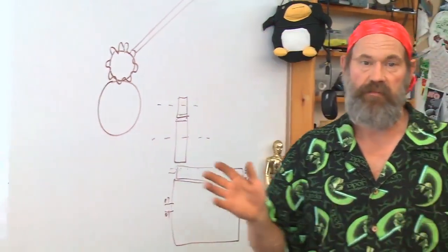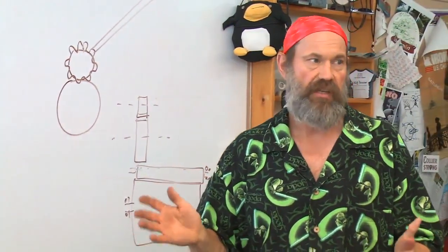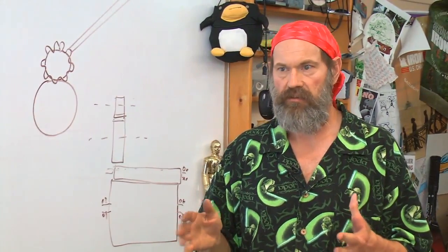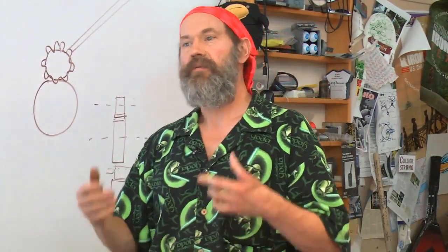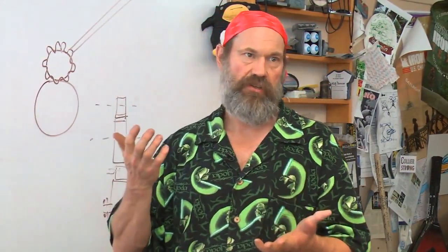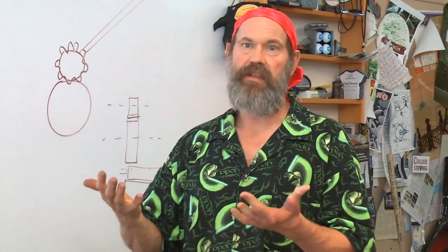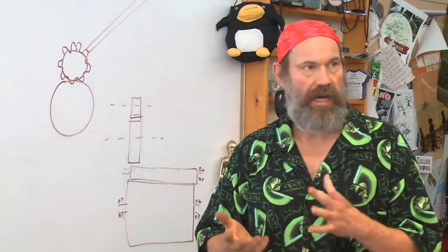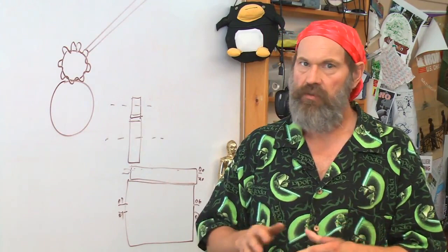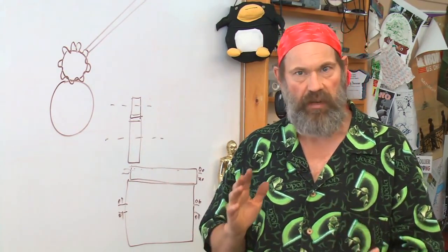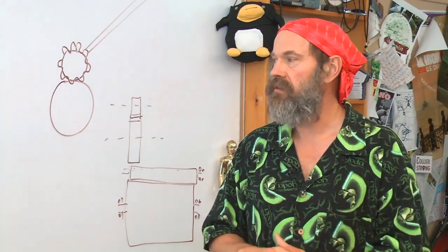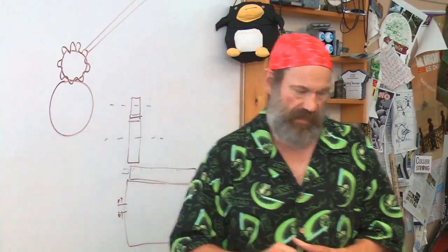In the vast majority of systems, your car, for example, you don't care that you have some backlash between the gears because you're always moving in one direction. And when you stop and go in reverse, you don't notice, you don't really care about a little bit of that backlash. In a high-precision robot or machine tool, you can't tolerate that, so you need a way to preload the gearbox. Many different ways of doing that.